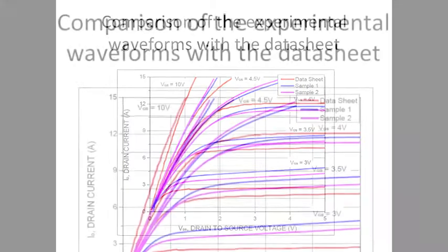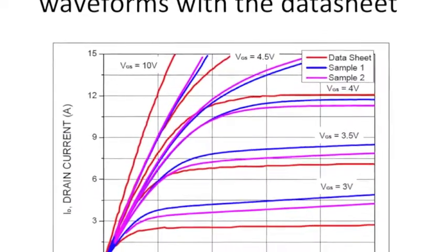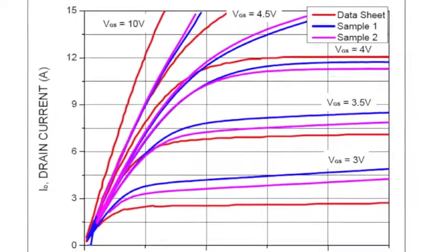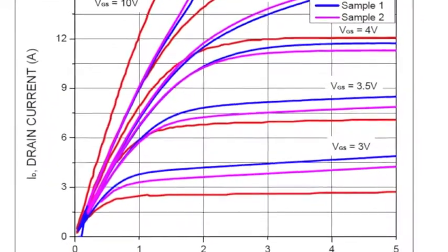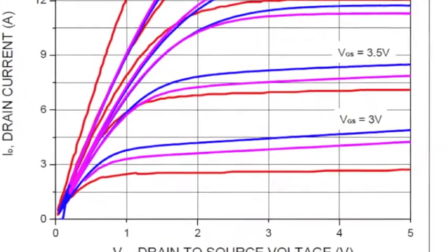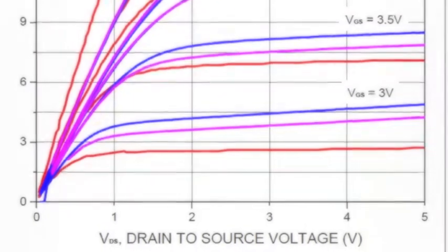As you can see, there is a variation between the experimental measurements and the data obtained from the datasheet. That variation can make huge differences between the simulation and the real behavior of the inverter, especially working at such high frequencies. Again, this is the reason why we want to do the modeling based on experimental measurements.